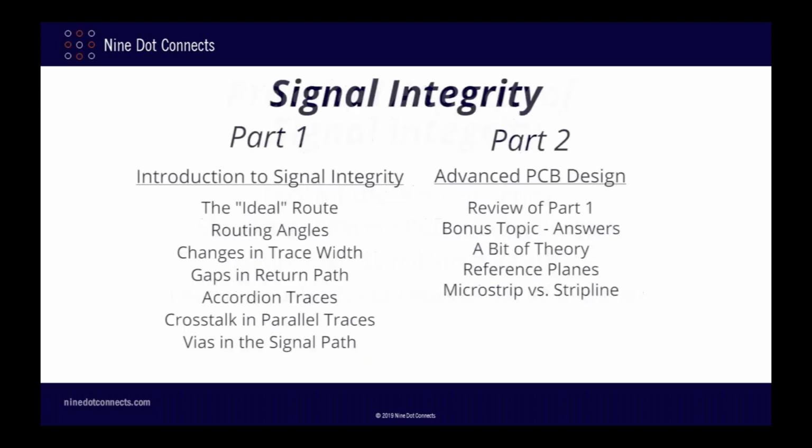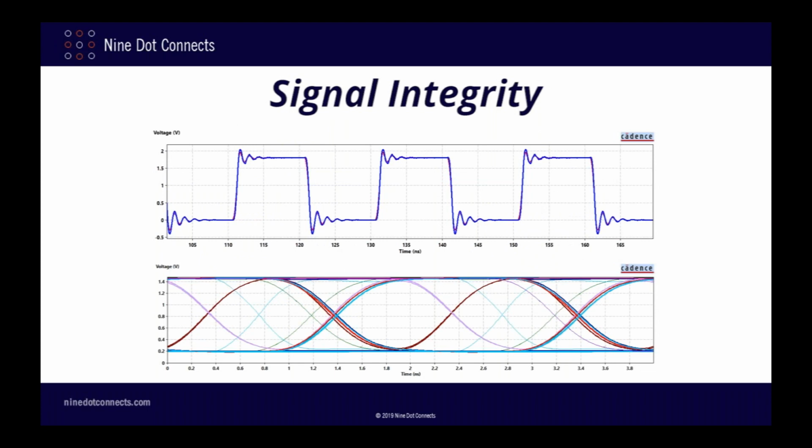In parts 1 and 2 of this series, I've focused on the analysis of the signal integrity aspects of a single element associated with PCB routing, such as the trace size and length, the use of vias, how reference planes work, and so on. We were interested in seeing how the signal integrity of the physical aspects of these different PCB elements would affect the signals, causing effects such as signal degradation, ringing and overshoot, increased rise times, and so forth.